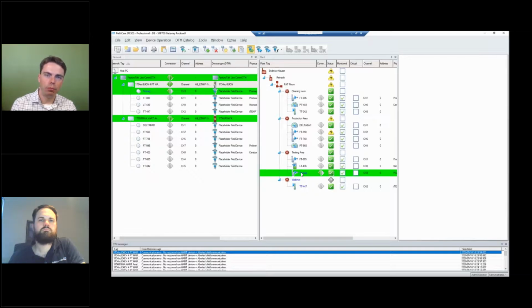In case there is no Profinet, no Profibus, or no Ethernet network that we can hook onto to get access, we also have the option to place modules in front of traditional IOs that strip off the HART signal and convert it to Ethernet. That way, we can also integrate legacy installations. Maybe you have installations where you don't have HART at all, so there is no HART-capable card in the DCS or PLC.